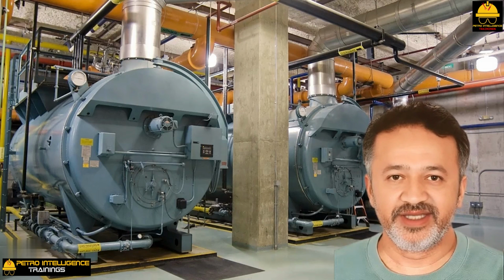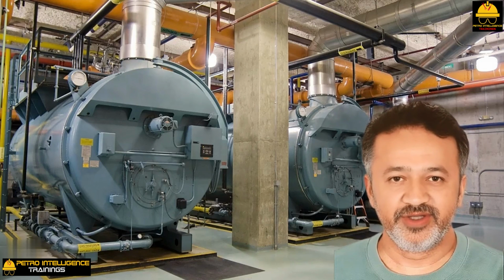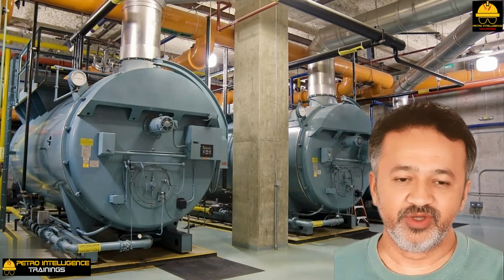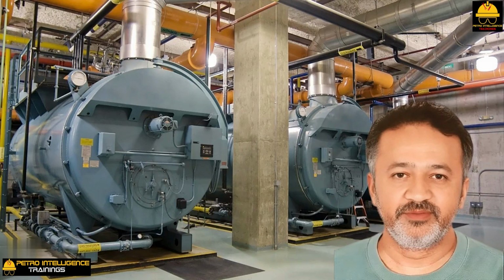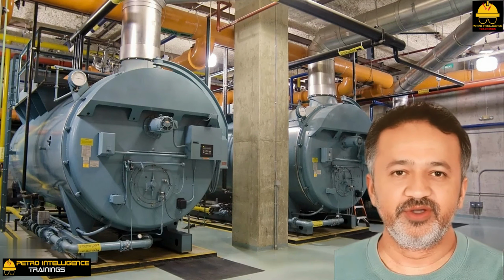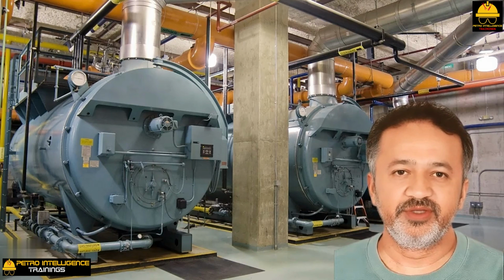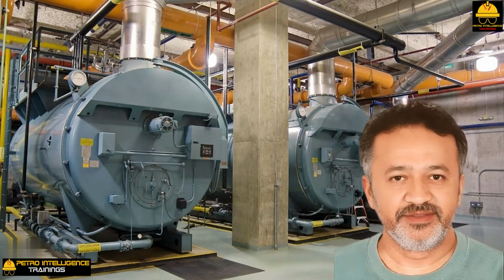Entrainment of high TDS boiler feedwater into steam from a boiler is promoted by excessive pH. Caustic is often added to the feedwater to reduce corrosion. However, if the pH increases much above 10.5, then the boiler tends to foam, and hardness deposits are carried over into the steam. Hardness deposits degrade the performance of steam ejectors, steam superheating coils, and steam turbines.